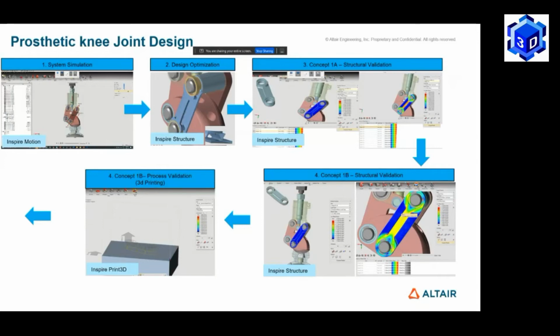So the FEA for that person needs to be designed into an implant. The acetabular component does not require a lattice from the FEA point of view, because the entire cup gets integrated and the weight transmission predominantly goes onto the entire semicircular part. For the acetabular cup, all you need is to create either a lattice or a trabecule which will only enable osteointegration. Correct.